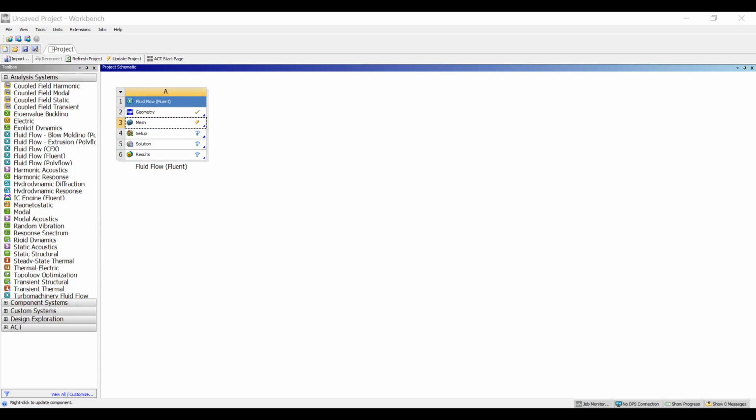And then the one last thing that we'll do just in a second, once this finishes meshing, is while we're in here, we'll go ahead and define our boundary layers so that we'll be ready for that once we get to Fluent and actually simulating the flow. We'll need our velocity inlet, our pressure outlets, or inlet and outlet. We'll just need the 2 walls on the upper and lower surface. Those are symmetry walls. And then the wall around the cylinder will just be our cylinder wall, is what we'll define that as. And so once this is done, we'll go ahead and do that.